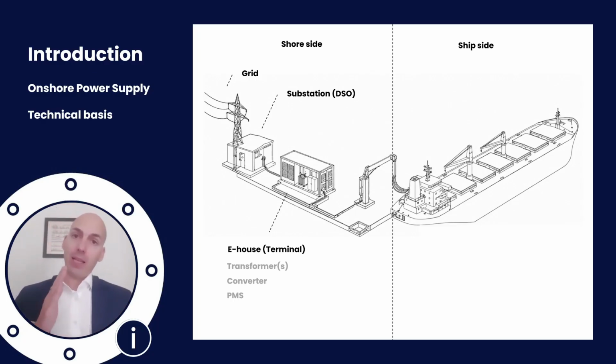And like I said, in EU we have 50 Hz frequency in our grid, and ships, most of them use 60 Hz. Typically also need in the EU a converter, and sometimes we also need 2 transformers if we have a pre-step up and a post-step down transformation, or vice versa.